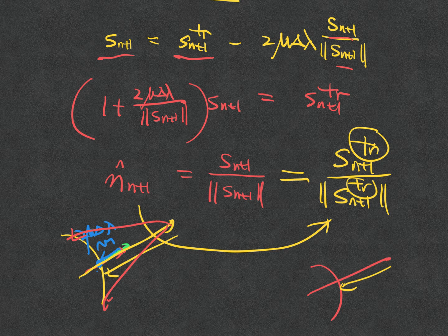Does that make sense? The entire return mapping algorithm only predicts one thing. I only need to solve one thing. And what is that one thing? Delta lambda, okay? And delta lambda is a scalar. So if I can update delta lambda, the whole thing is updated. Does that make sense?